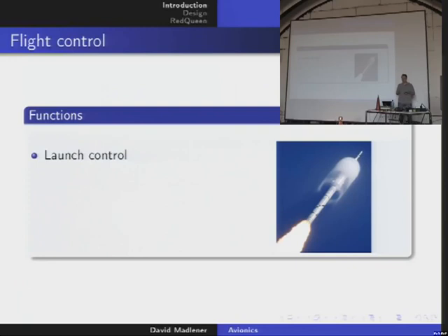If the avionics tell them that everything is going to be fine just before launch, then when it starts, you have attitude control. So normally very heavy rockets, this one it's not very heavy, but very heavy rockets normally always lift off just vertically. This is because if you would lean them a little bit to the side, they would just break in the middle. And they cannot support themselves if you put them under gravity loads. So they really have to start vertically, but they don't want to go upwards. They want maybe to orbitalize, so they have to change the attitude during ascent.